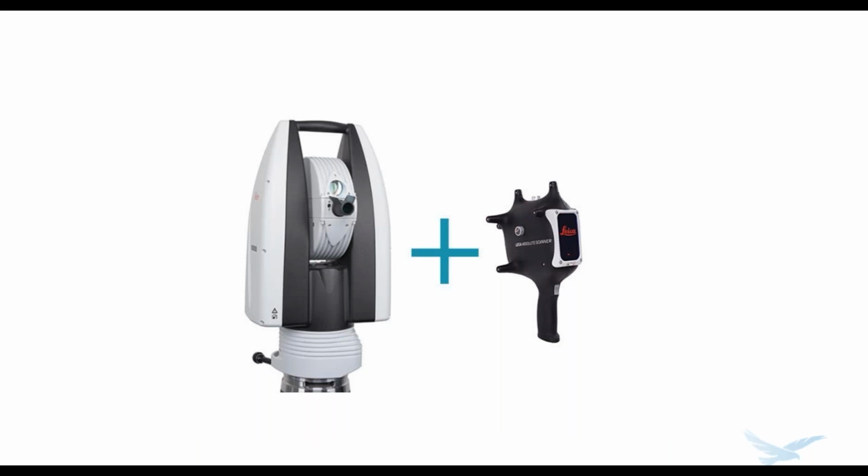Another related tech is a laser tracker. So instead of firing out a bunch of points, these tend to fire a single beam out. And these are even more accurate over long distances than LiDAR. And these can be used like a giant coordinate measuring machine, where you can walk from one end of the building to another and touch off points and know the distance between them really accurately. So if you wanted to measure between two pipe flanges across long distances or something, these could be really good.